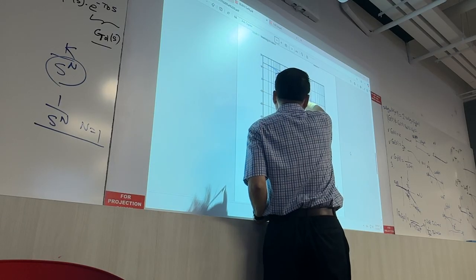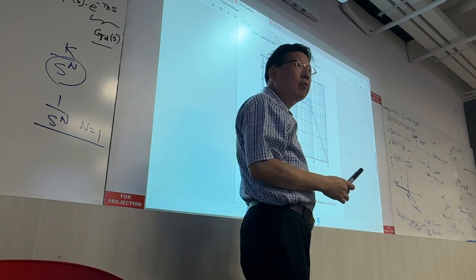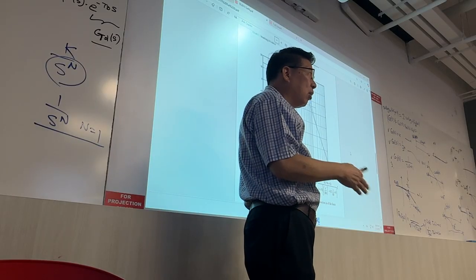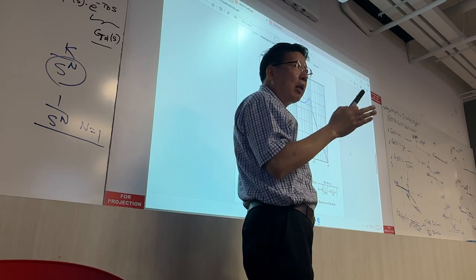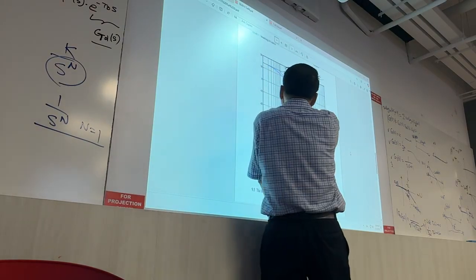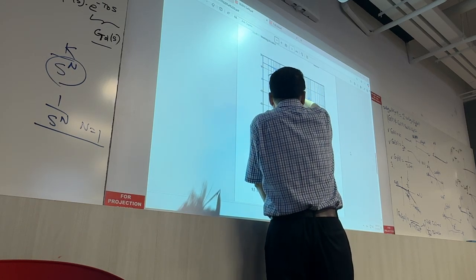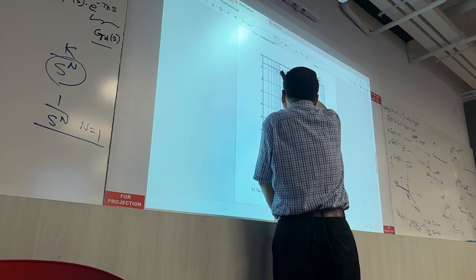Even though you get a very good fit, it is not a multiple of minus 20 dB per decade. There is not the fixed slope. We need lines of minus 20, minus 40, and so forth. So even if you don't get the perfect fit,